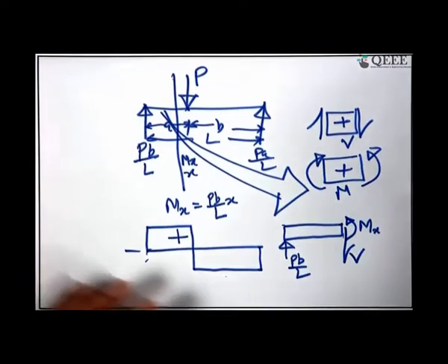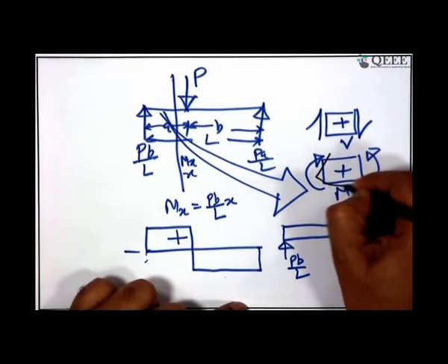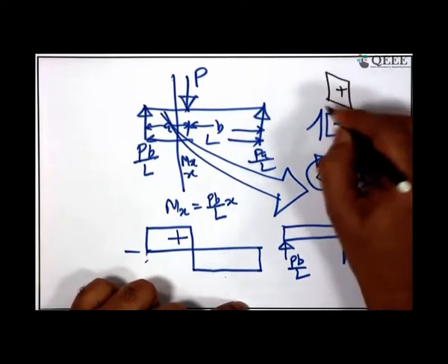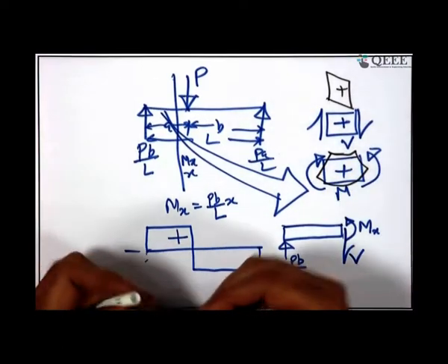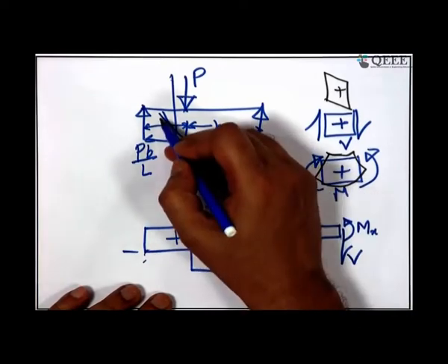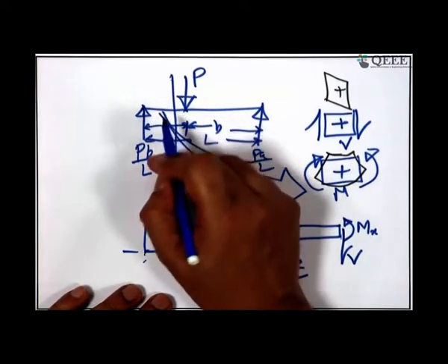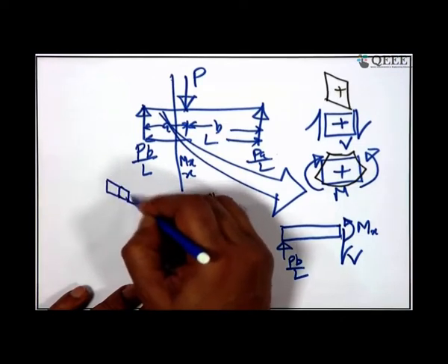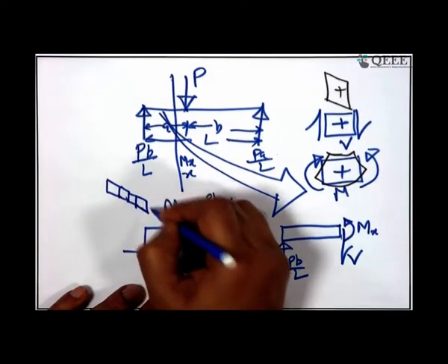So, I should have another color. It tries to bend it like this when it is bent, and this tries to distort it like this when it is left up, right down shear, and this if I take it positive. So, if I take it positive, then this shear force, in the absence of bending moment, will try to bend the beam like this, in a rhombic way.